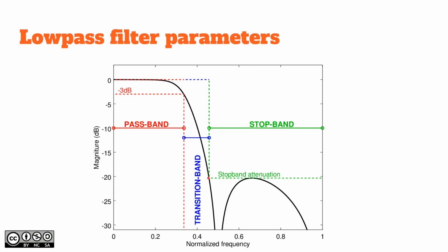So practically, in this picture, if our requirement for stop band would be 15 dB, then our stop band would start a little bit earlier. So basically the same thing as the passband. This is where the passband ends, that corner frequency, it's defined by some dB level.